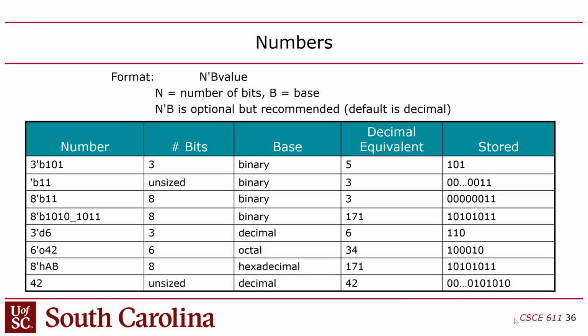Okay, so this is, I think, where we ended up. In C and Java, you just generally work with a few different standard native data types, right? Usually 32-bit integer or 32-bit float, 64-bit float, right? But when you design hardware, you can specify how many bits every signal is because you're physically creating wires for those, or registers, or memory locations, right?